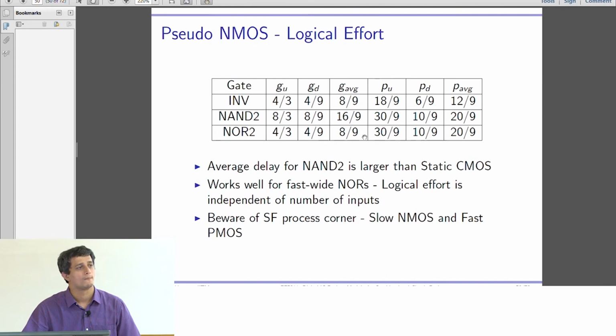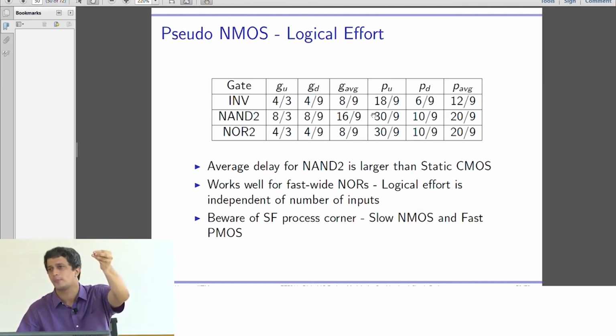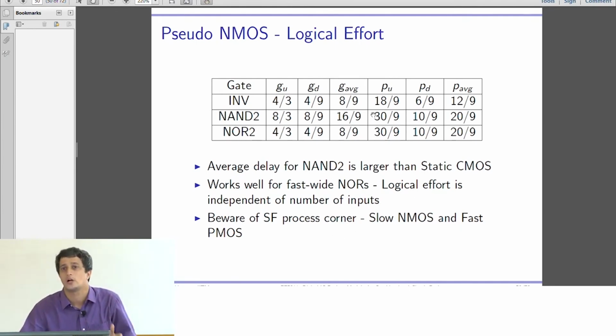Okay? Clear? Now, parasitic delay is what? You're going to count diffusion capacitance divided by the diffusion of that reference static CMOS inverter that we constructed. So, work this out as well. We can discuss it in a tutorial session later. Clear?